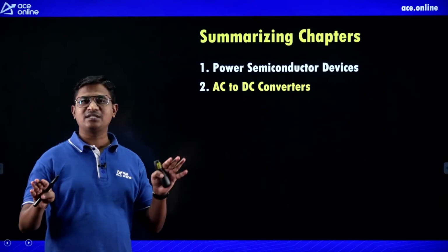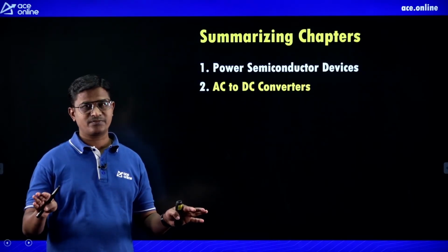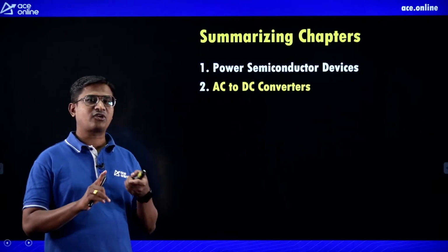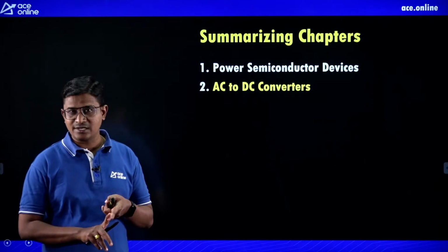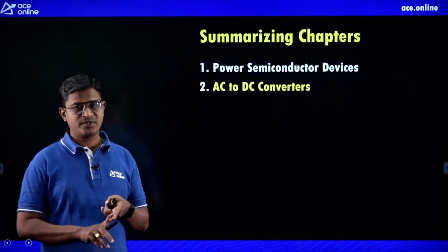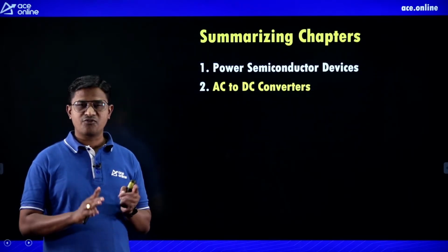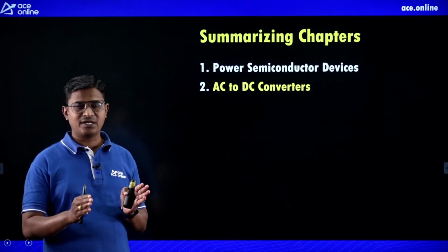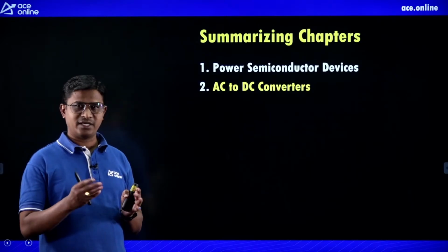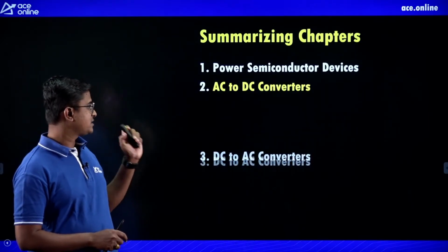Also in single phase and three phase we have the semi converters. In addition to that, effect of source inductance, and input power factor for RL load and RLE load. If the load is highly inductive, how to find the input power factor? Input power factor is the distortion factor times the displacement power factor, etc.